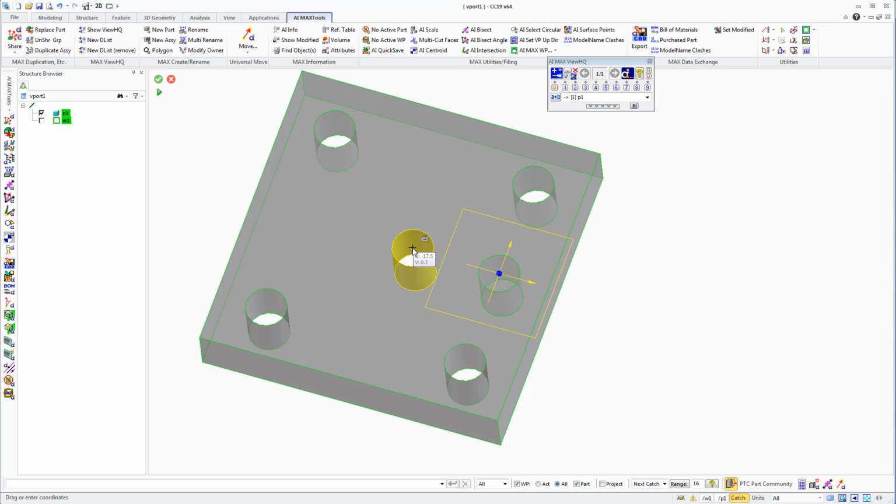So now what we will do is hit the letter M while we're in this 2D mode, and that will allow us to put a line between 2 points. So we have the center point of this hole and the center point of this hole over here, and notice it draws a line and it shows us a midpoint here that we can use a little bit later. We'll hit M one more time, and we'll do the same thing with these top holes.